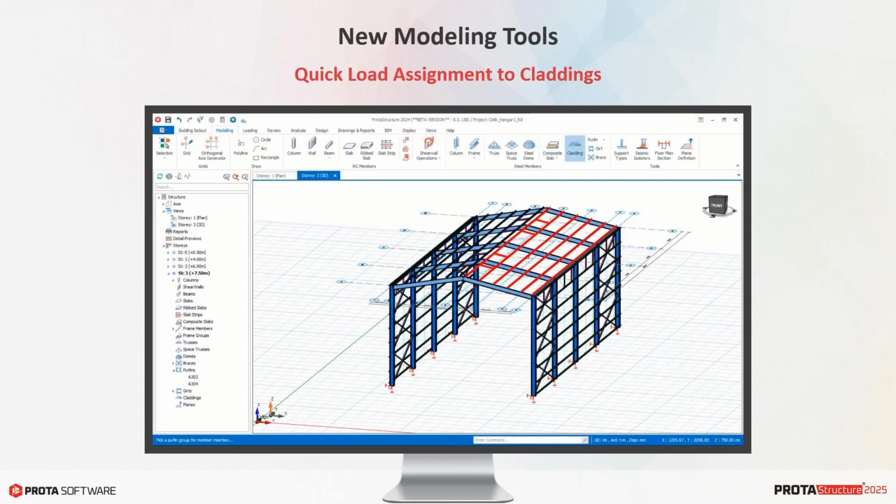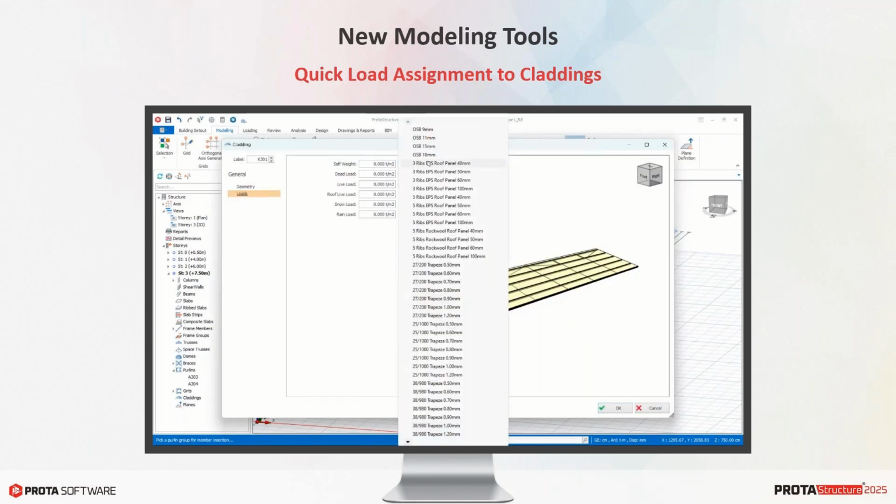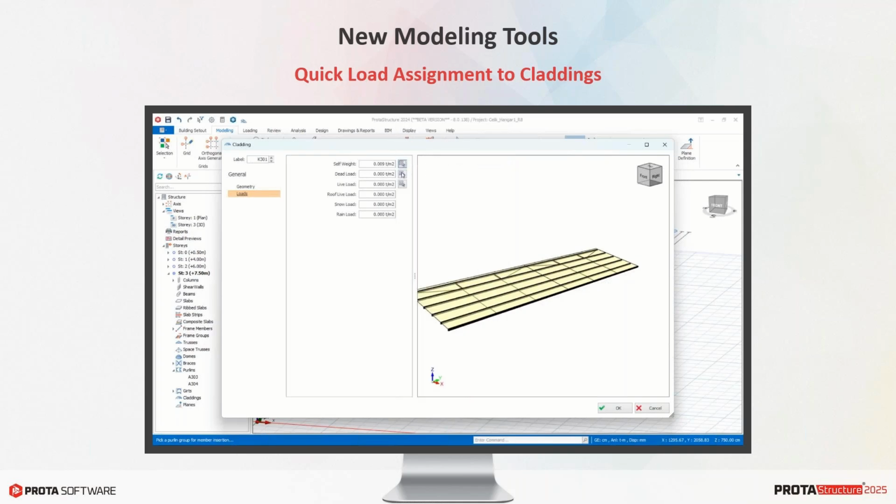Again, with this new version, now you can directly assign area loads on claddings using the modeling interface. To make it even more practical, we have included predefined load libraries. To define self-weight, for example, you can select a sheeting from the library. So for self-load, dead load, live load, snow, rain, and roof load cases, you can simply enter the magnitude values to apply full area loads.